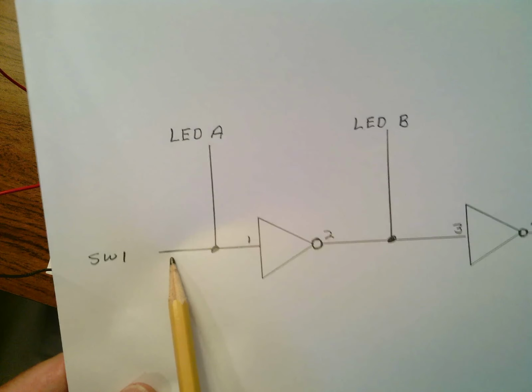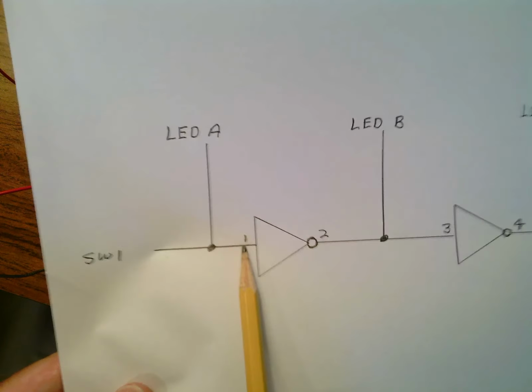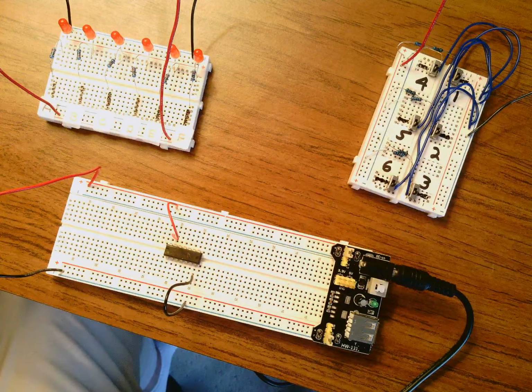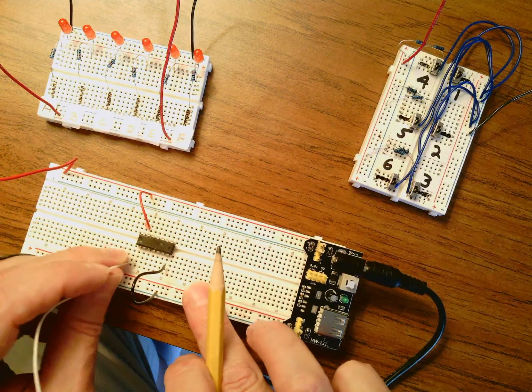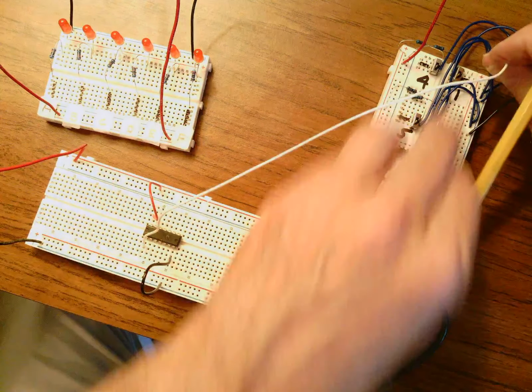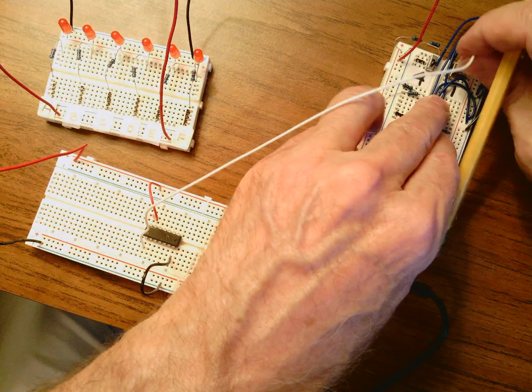So how are we going to build this circuit? First thing I want to do is go from switch 1 to pin 1. I gave you some nice long 15-inch white wires. You're going to take one of them and go from pin 1. You can use any one of these, they're all connected, don't forget. So I can take any one of these, that's pin 1, and I have to go to switch 1. I'm going to tie that to switch 1, and switch 1 is the middle section up here.